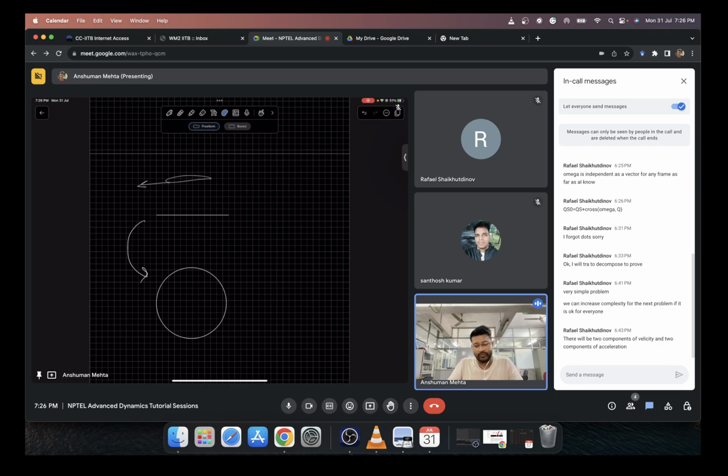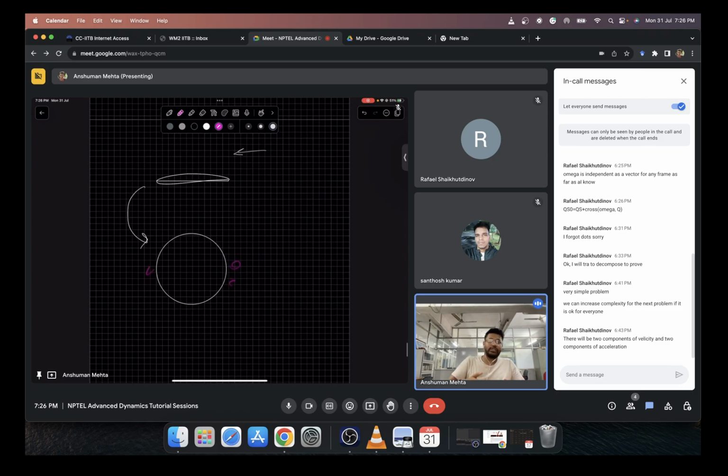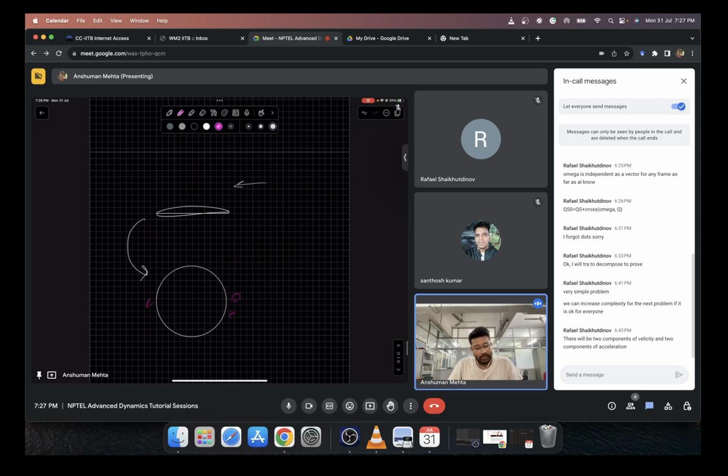But what we have to do is pin down the whole airfoil, and we will say that the whole world is now moving around it, so it's a flow past some bluff body or some streamlined body, depending on which study we are doing. Then we have to convert this whole airfoil into a circle, so that we can apply boundary conditions. So we have to change the coordinates. It all depends on that coordinate transformation, how we do it.